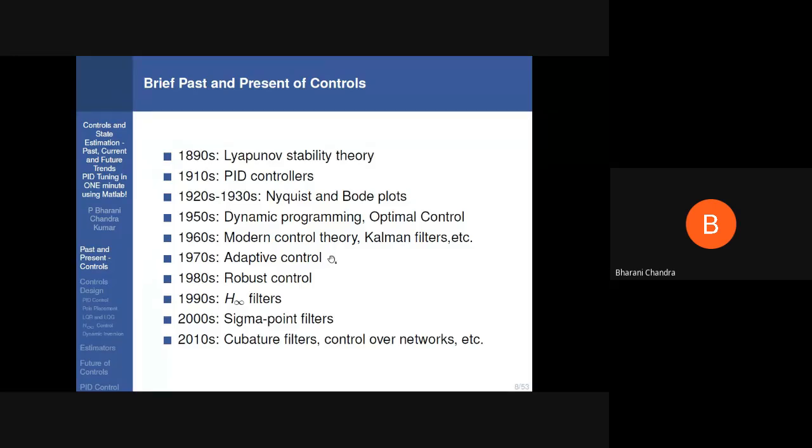However, in the 1980s, researchers thought that adaptive control is quite good, but the problem is that I should have a high computational processor because it needs to keep on changing the controller parameters with respect to the change in plant parameters. Robust control is different, though it can also deal with plant uncertainties. Here the control structure and control parameters are constant, whereas in adaptive control the control parameters vary with the change in plant parameters.